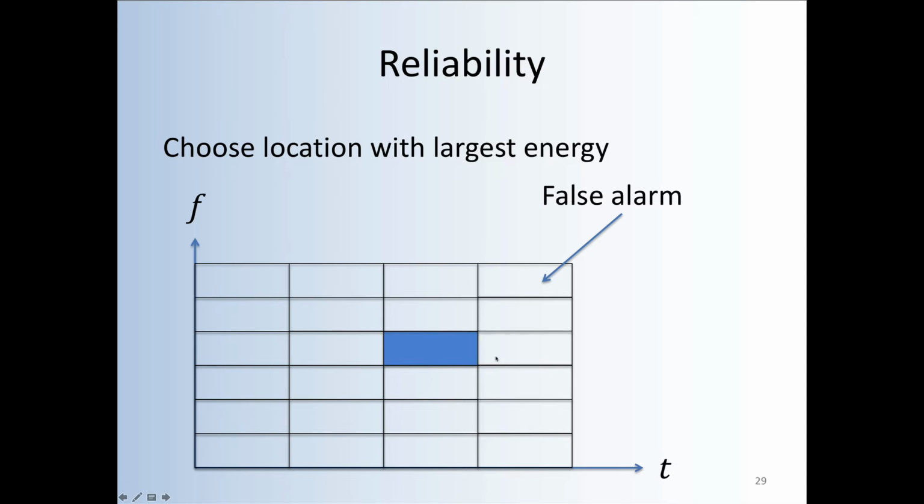So the objective of minimizing the energy leads us to the conclusion that we should use a signal of this type, which is the so-called OFDM, orthogonal frequency division multiplexing. The second observation is that the use of this location coding, where we have this sort of sparse location of energy within a grid, and we're communicating by location rather than phase or amplitude, is also dictated by the desire to achieve low energy.